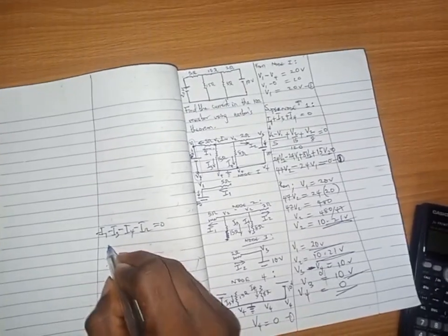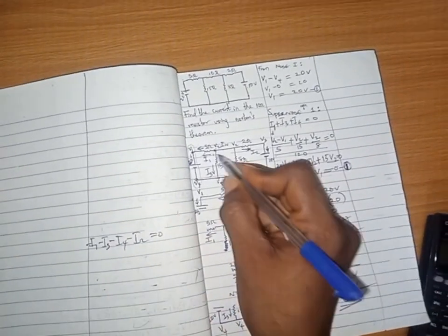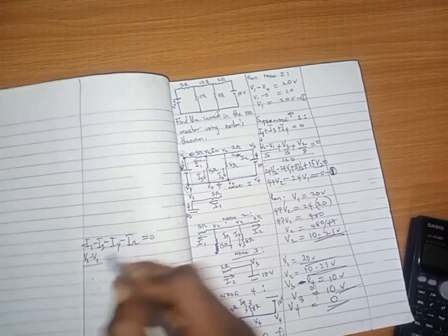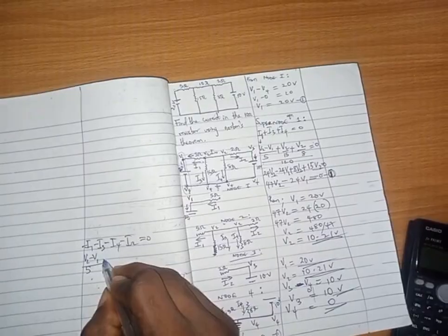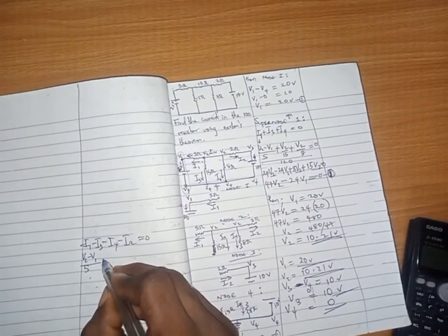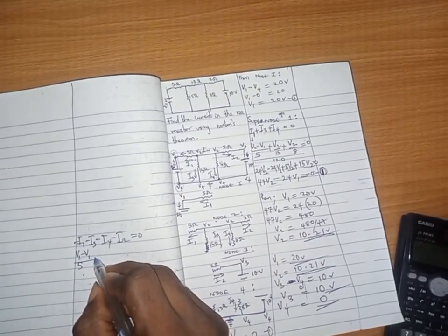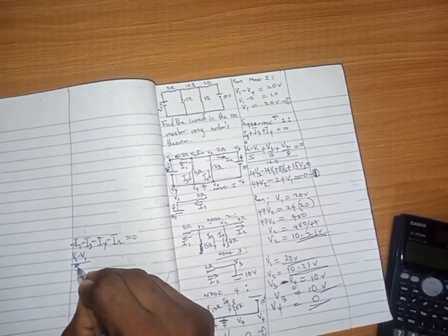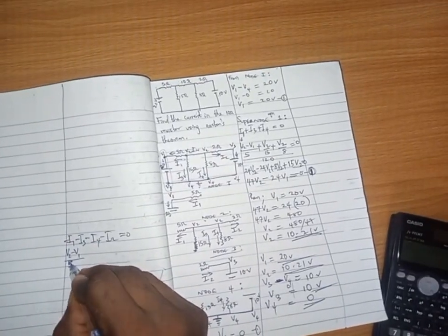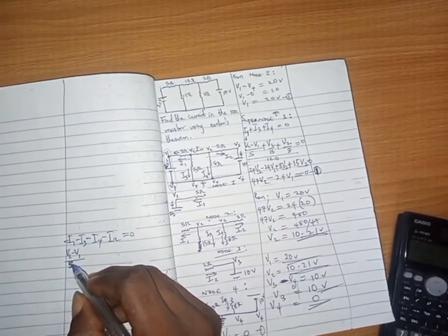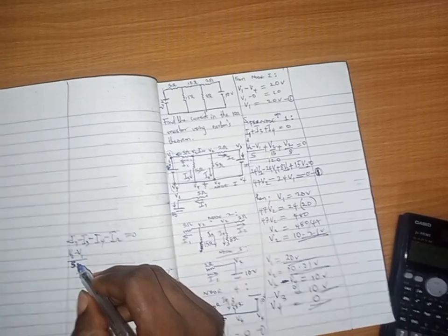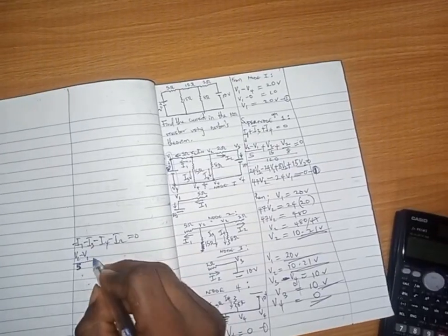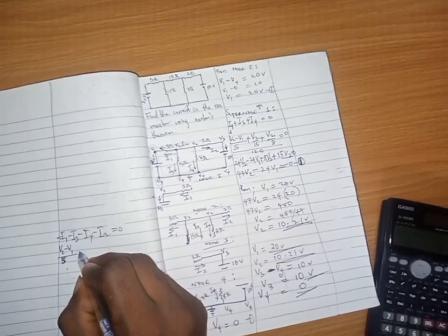So let's get I1. I1 is in between V2 and V1, so V2 minus V1 all over 5. I'm just checking to see if I can get V2 from this on the second node, but I've already gotten it. This is a better approach, simply following the rules. If I get a node and that node is gotten by doing the voltage up minus voltage down equals the voltage in the middle, get the super node immediately. So following the rules, that's it. We're just making mental assessments. That's what we're doing here.